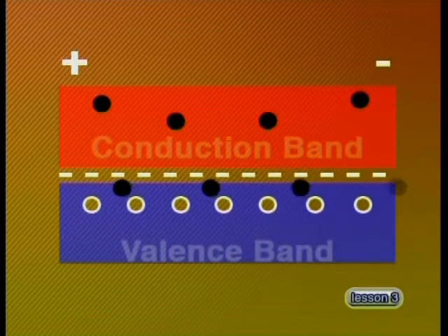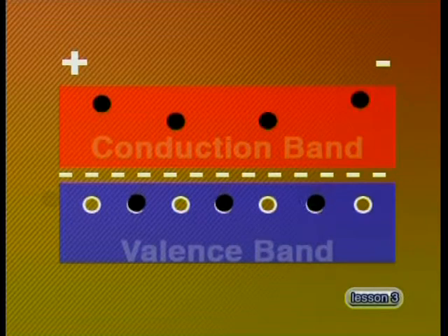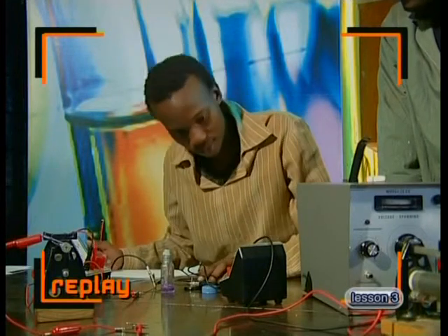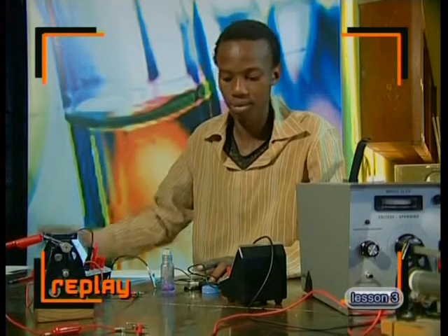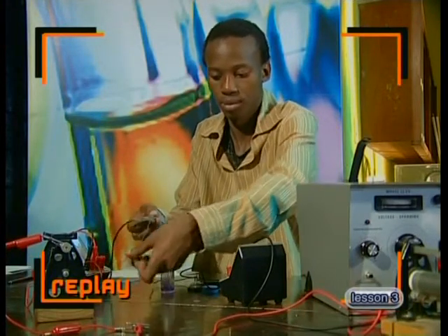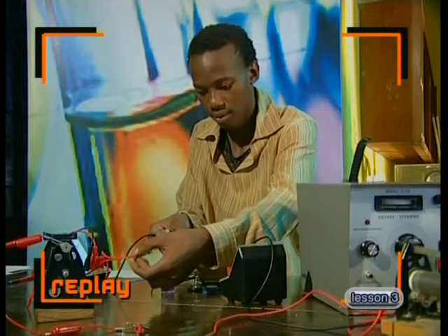Notice that the direction the electron moved in was towards the positive terminal of the battery, but the hole, or positive charge, appears to move in the opposite direction, towards the negative terminal. The apparent movement of holes in the valence band, together with the movement of excited electrons in the conduction band, is the reason you detected a current passing through the silicon when it was heated.